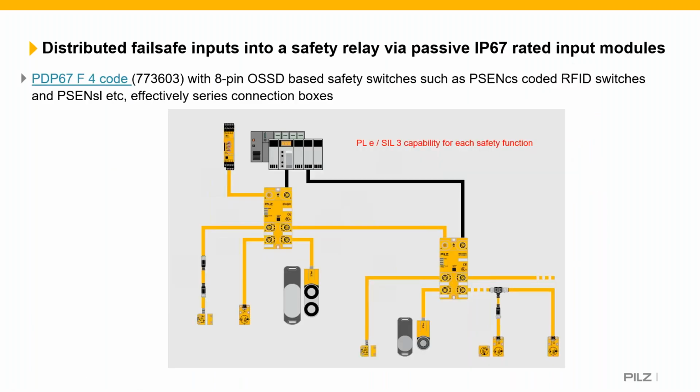You can also use distributed fail-safe inputs into a safety relay via passive IP67 rated input modules. The Pilz PDP67 units operate with 8-pin OSSD-based safety switches, such as our PSEN CS RFID coded switches and our PSEN S-locks, and they are effectively a series connection box.